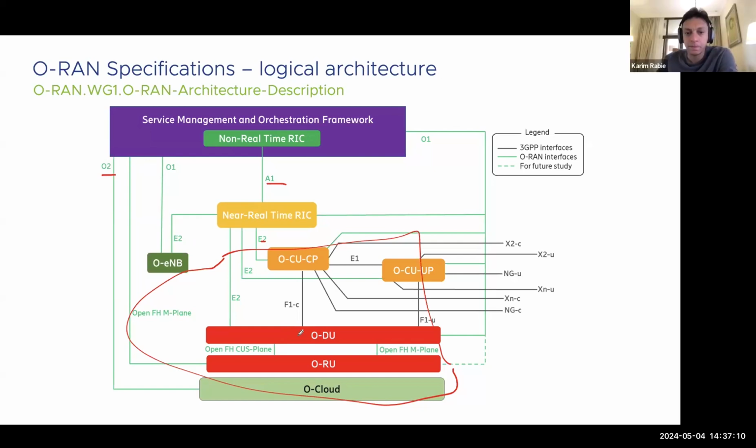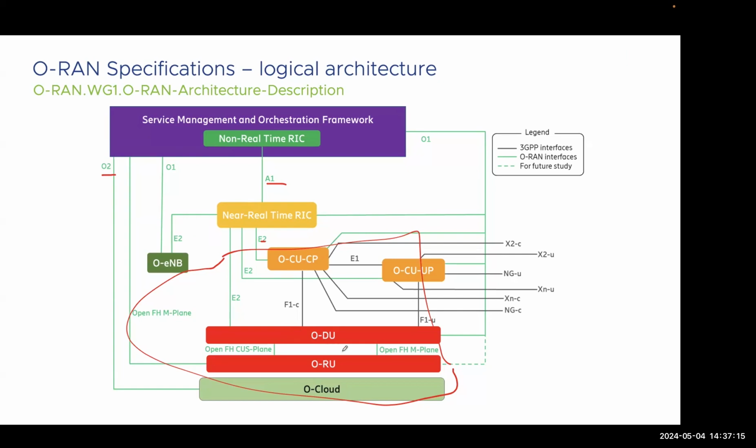Thank you, Sherif. Just to be aware, all these standards in the open fronthaul are part of Work Group 4. We mentioned that there are 10 working groups. Work Group 4 focuses on the open fronthaul specification and the famous 7.2x split. In 3GPP there was something called functional split, and for the fronthaul communication they selected 7.2x, which matched the eCPRI way very well.